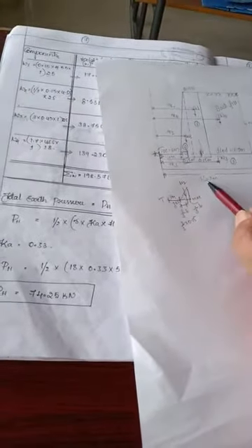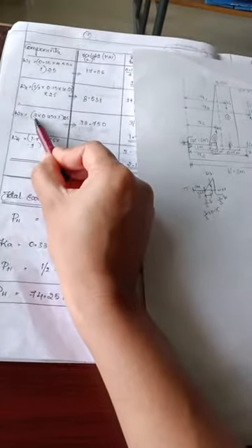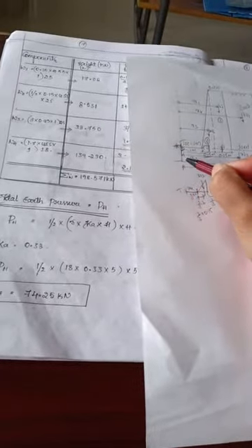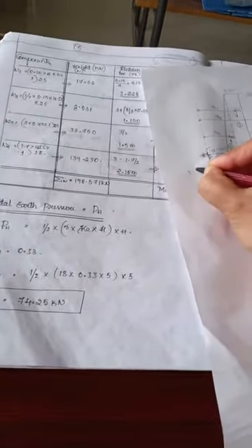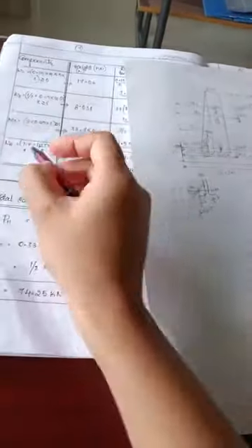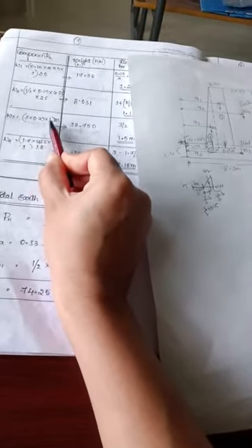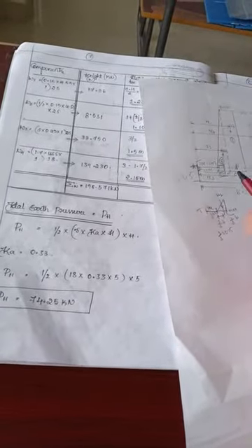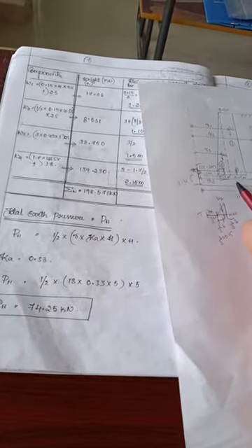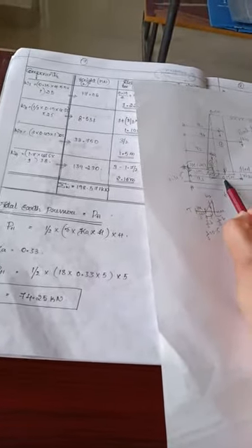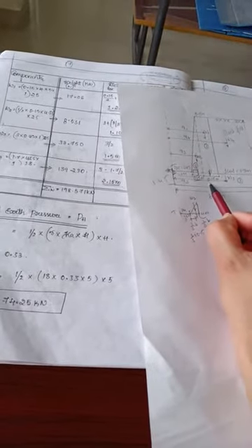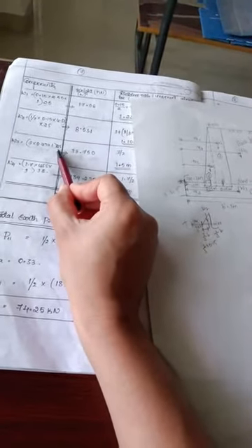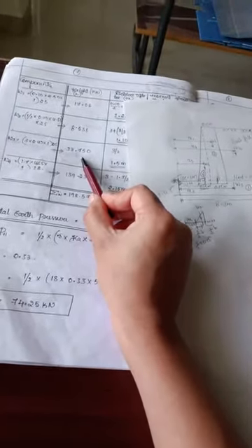Then the breadth value is 3 meter. After this, for height we consider the thickness of the slab. How much is the thickness of the slab? 0.45. Here 3 into 0.45 into 1. The slab is constructed using concrete, the material we use during construction, and the density of concrete is 25. After calculating these, we get 33.750.